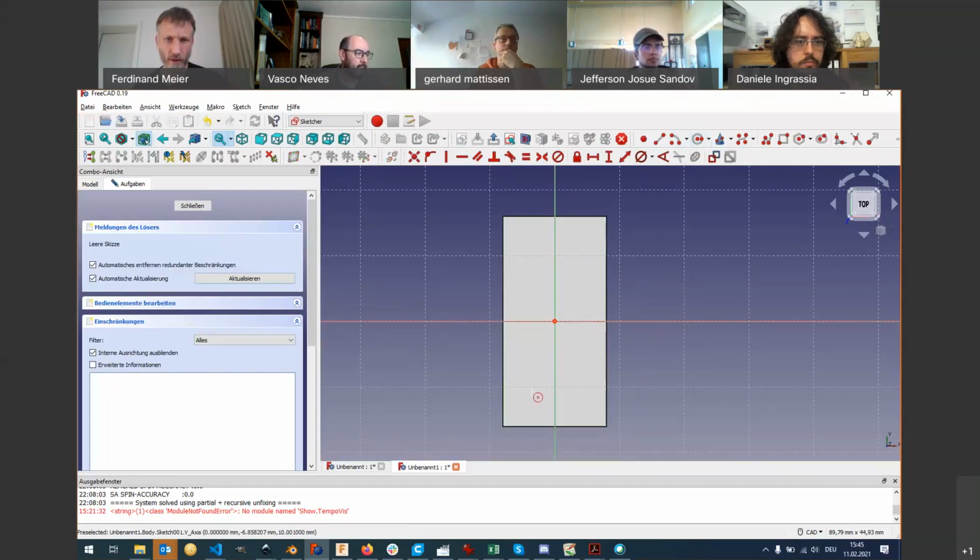I'm going to click once for defining the center, and then click another time for defining the radius. And I put it in the lower left corner, and I right-click for leaving the circle tool. Now I want to dimension the circle. And in Fusion, if you hover over one of the edges, it will automatically highlight those edges. FreeCAD doesn't. So if you want to pick an edge from down here, you have to use this tool that might be a bit hidden.